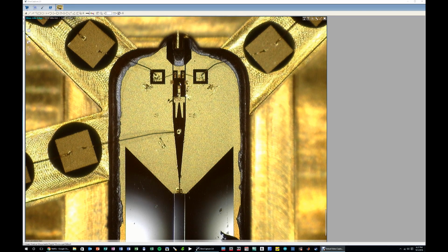So maybe there are 2 diodes back to back there. I'm not 100% sure because the architecture is really unknown, and there's some biasing signal coming in. Obviously all these also provide biasing at the same time to turn on this module, and then there's dynamic biasing so that it's precisely at the right point and so on, but it's pretty straightforward otherwise.